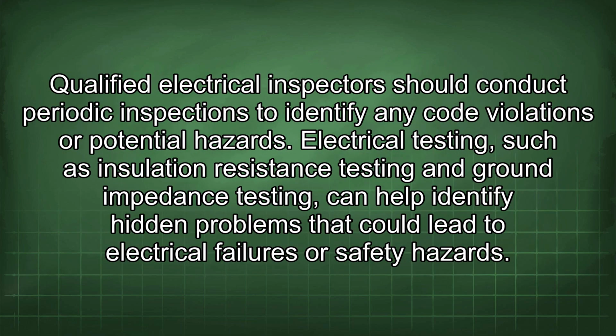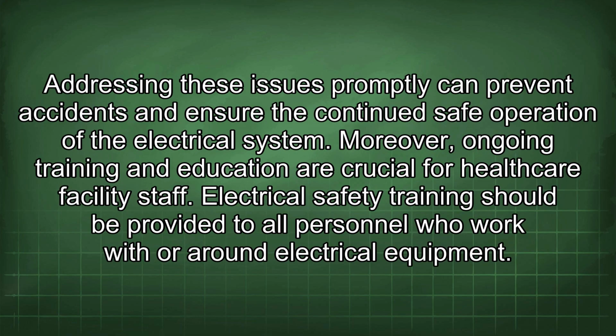Qualified electrical inspectors should conduct periodic inspections to identify any code violations or potential hazards. Electrical testing, such as insulation resistance testing and ground impedance testing, can help identify hidden problems that could lead to electrical failures or safety hazards. Addressing these issues promptly can prevent accidents and ensure the continued safe operation of the electrical system.